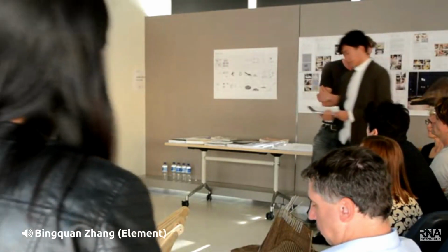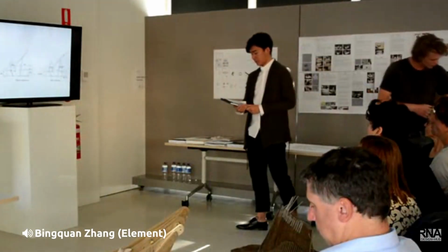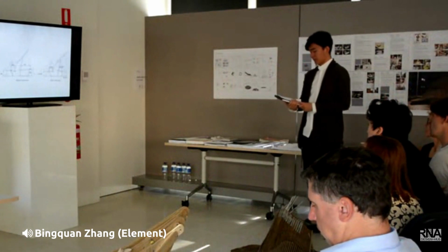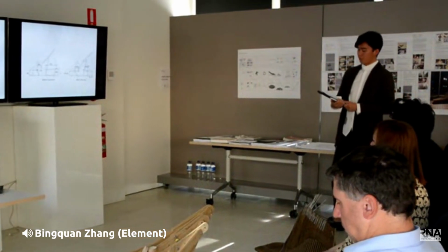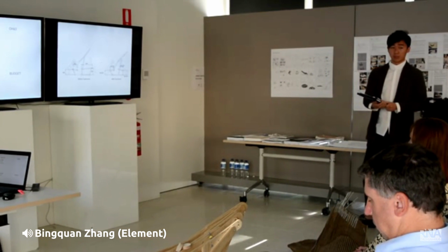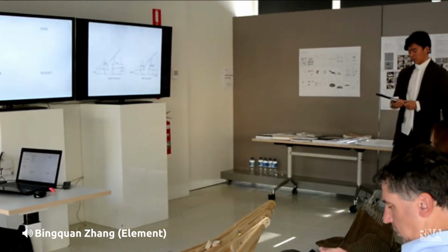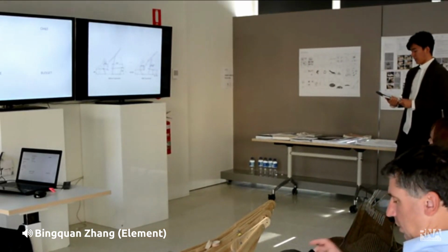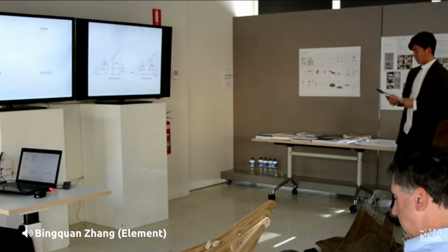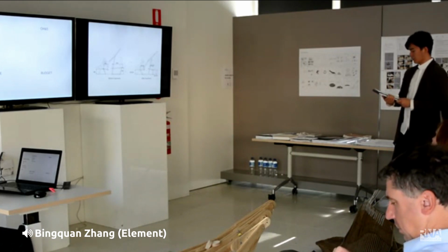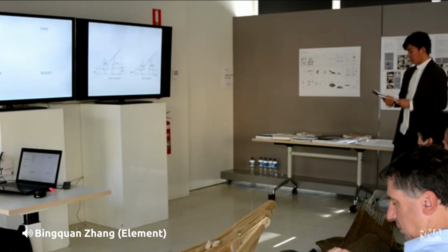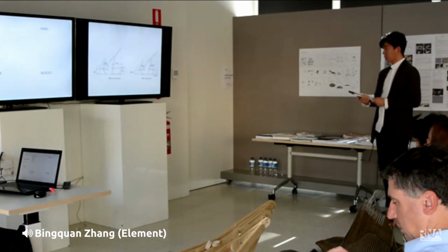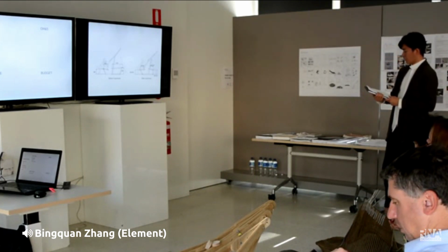So in terms of ergonomics, we tasked the pavilion section by section to analyze the size of the seat and the back. Because the original model is not suitable for people to sit on, based on ergonomic studies, we determined the size of the concrete seat. The seat is about 440 to 550 millimeters, and the height of the seat is around 380 to 550.